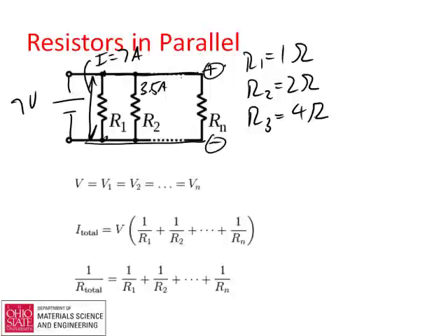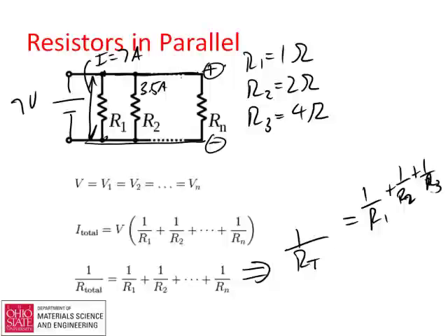So by putting the resistors in parallel, so that you have the voltage running across all of them at once, you see a much higher total current than you would in the other case. And if you work out the math for this, which probably goes beyond where you go, 1 over R total is equal to 1 over R1 plus 1 over R2 plus 1 over R3. So you can do an equivalent circuit that way. Okay, and I'm not going to go into that. That's fairly simple. Lots of places cover this.